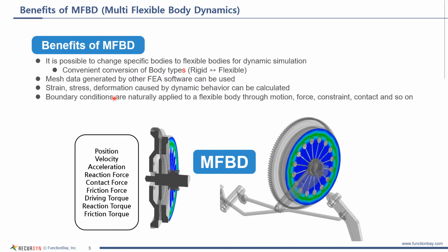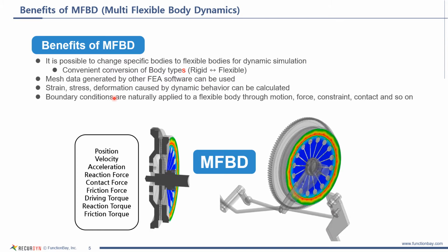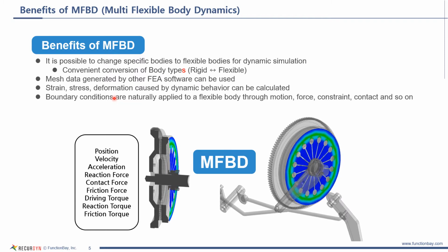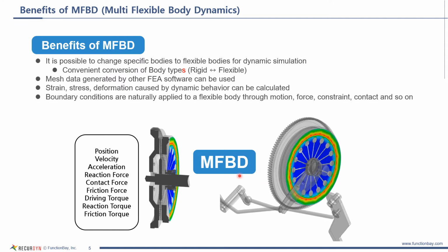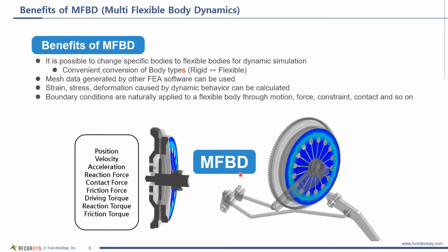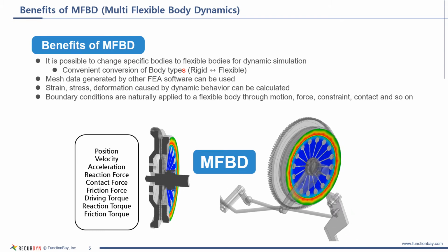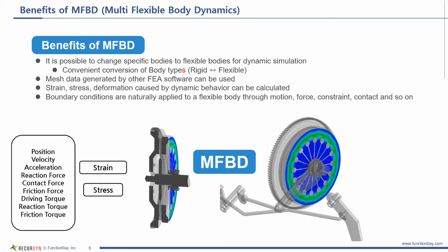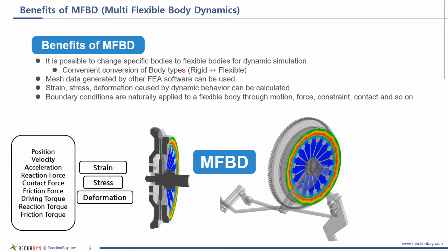Boundary conditions are naturally applied to a flexible body through motion, force, constraint, contact, and so forth. As you see, if you simulate a model after converting a rigid body to a flexible body, not only the position, velocity, acceleration, but also the strain, stress, and deformation are calculated.